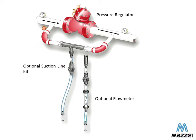Let me highlight another piece of information here. This piping that is connecting the injector to the main line, if this is, for example, a 2-inch injector, then this should be at least 2-inch piping. You don't want to have piping connecting to the injector that is smaller than the connection size of the injector itself. And the same thing goes for the suction tubing. If you can connect it up to the injector and you're not reducing it from what the injector's hose barb is naturally here, then you're in good shape.